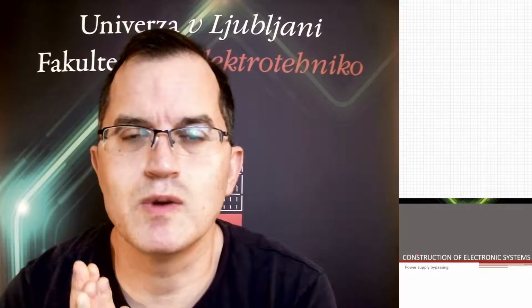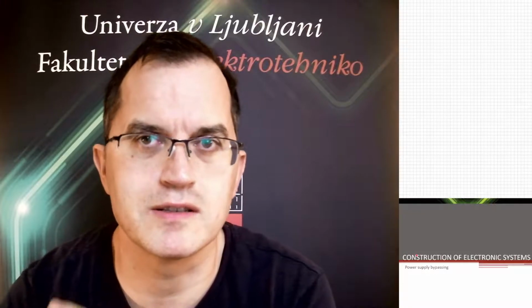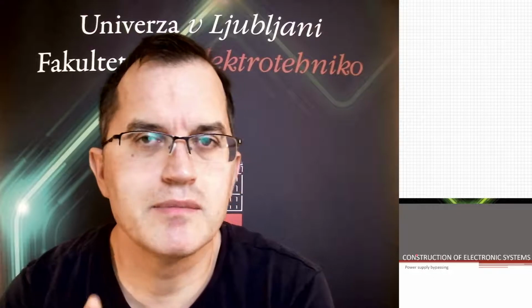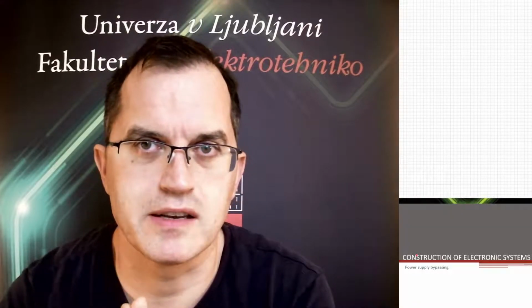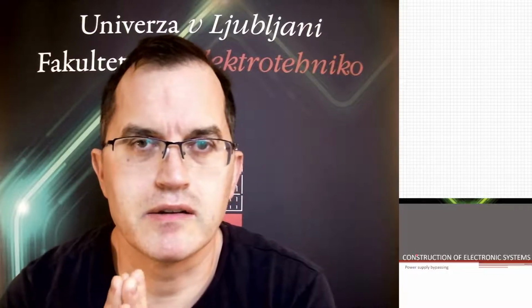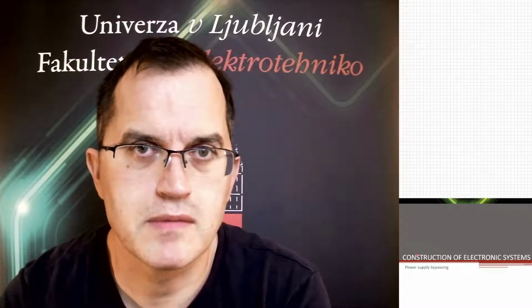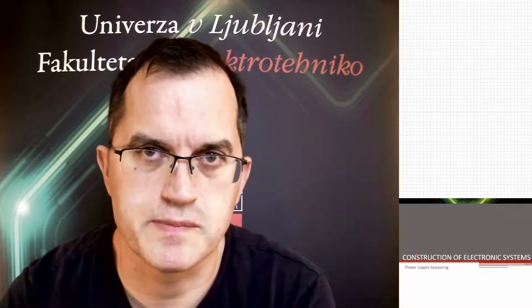It means that you want to make a very stable power supply voltage for all the circuits in the PCB. And that can be achieved by using a special technique called bypassing. Bypassing requires capacitors that are placed very carefully, and these capacitors then supply the stable voltage to all the circuits.